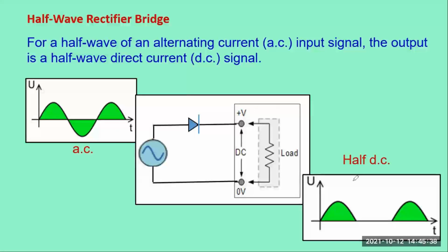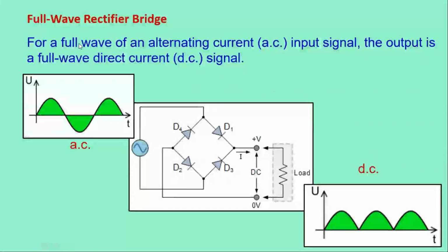So in reality, the half-wave rectifiers are used with a filter such as a capacitor or inductor that will smoothen these ripples and make this pulsating DC applicable in many normal uses. So we can also look at the full wave rectifier.